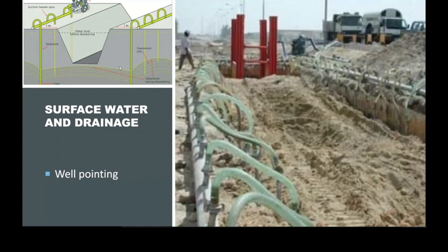So what they had to do is what's called well pointing. They have all these shafts stuck in the ground around the area that you're going to work, which are basically filtered tubes. They're all hooked up to a big manifold that's hooked up to a big surface pump. Usually it just looks like a big box.